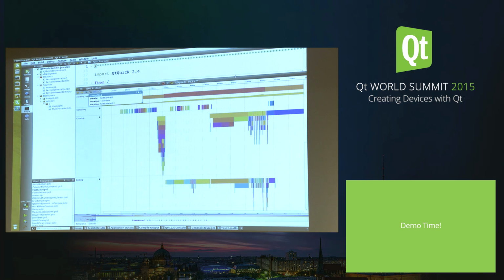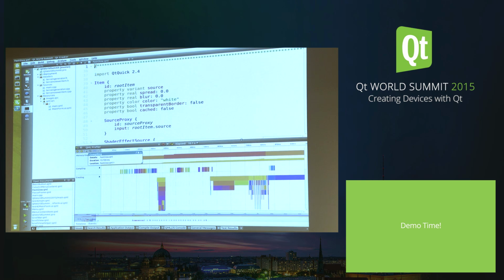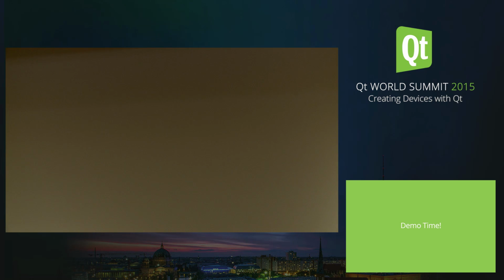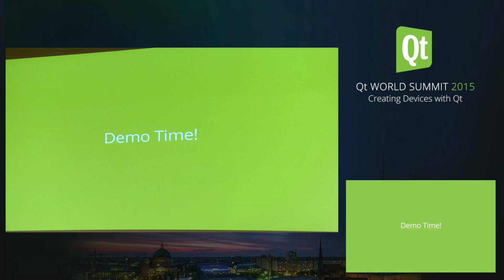Yeah, so we also have support for some CPU profiling. In the case of the embedded device, this is going to be the O-profile style, polling CPU profiling, because if you're running something like Valgrind on an ARM device, it's potentially slow enough already in debug mode, and if you add an additional layer there, you're going to have quite a bit of trouble. But okay, I think as far as demonstration goes, that's what I have for that.